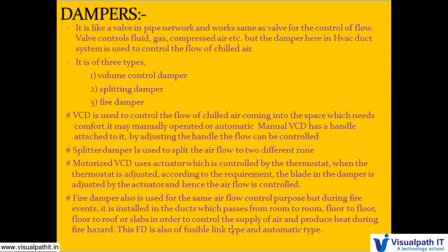Fusible link type will have a wax type component already installed in the damper itself. Whenever there is a fire hazard, due to the increase in heat, the wax type component I told you about melts, so that the shutter comes down and it stops the movement of air.